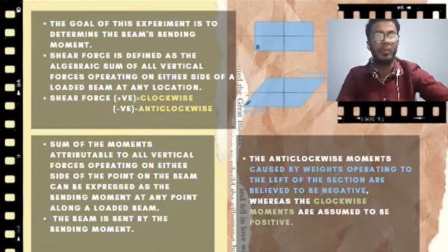Shear forces are considered positive if they produce a clockwise moment, and negative if they cause an anti-clockwise moment. The sum of the moments attributable to all vertical forces operating on either side of the point on the beam can be expressed as the bending moment at any point along the loaded beam. The beam is bent by the bending moment.